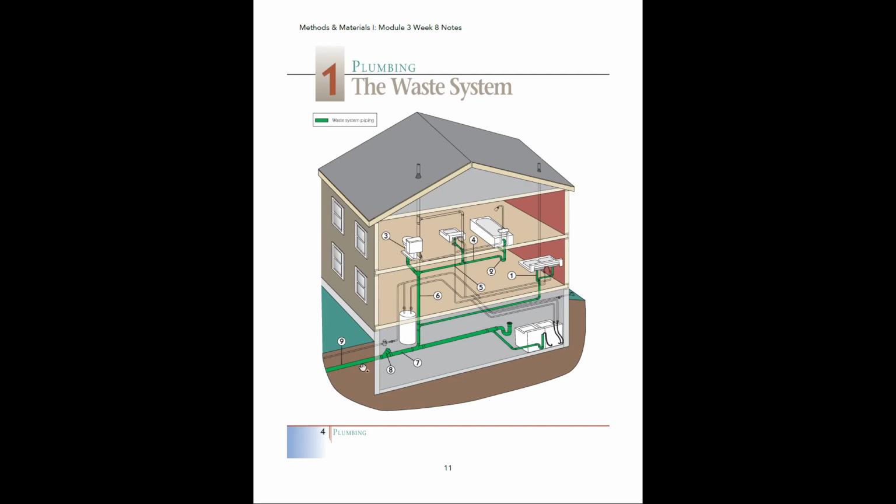So we're looking at the basement floor here, and underneath the basement floor we're going to have a drain pipe laying under the floor, and everything coming from the soil stack or any other fixtures off of this main drain line will be tied into it, and anything that is exiting as waste will leave the house through that main drain line and go out this way to the sewers or to a septic tank, depending on where this house is located.